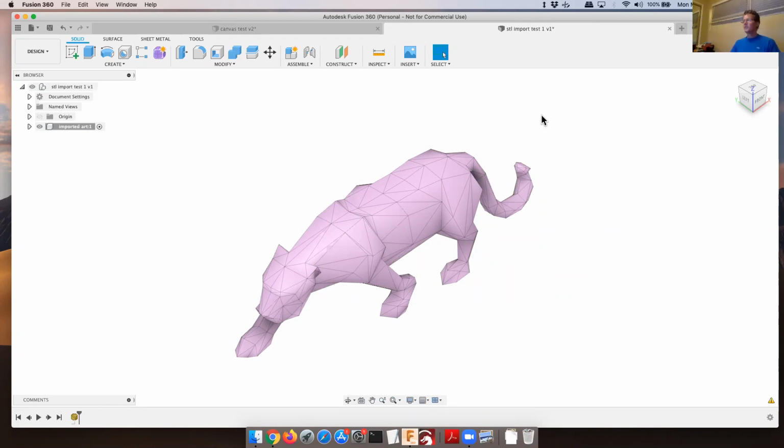The reason you need a solid is if you're going to make modifications to the object for the purpose of changing what solids are going to be printed out, then you need a solid to make those solid modifications to. Because you can't hack an STL, you need to have something that is defined as solid to be able to bore holes in it or chop it in half or those kinds of things. Is that what... Exactly. Okay. That's exactly it.